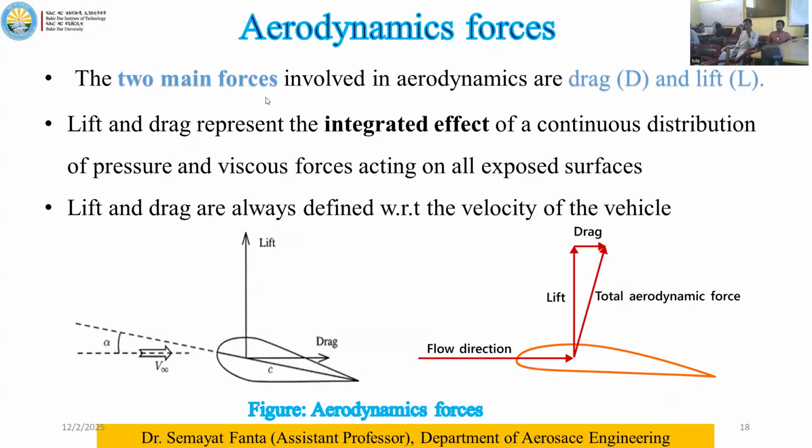So the two main aerodynamic forces involved here are the drag force and the lift. Actually, the others are also forces, but thrust is the propulsive force. It is due to the presence of power generating systems or the engine, so we cannot directly consider it an aerodynamic force.